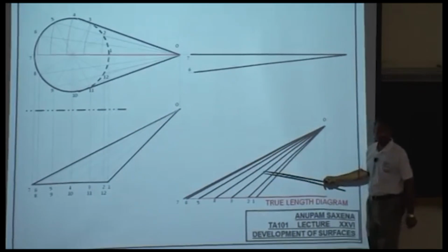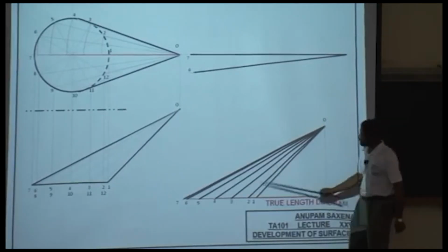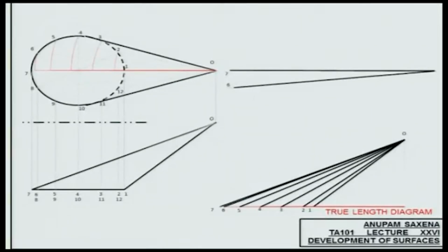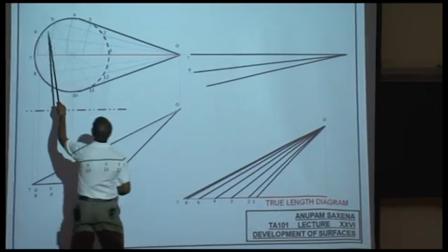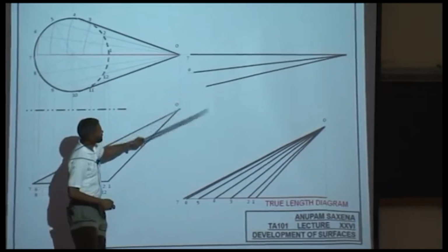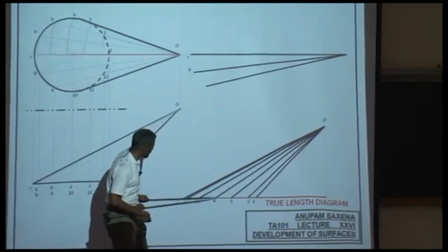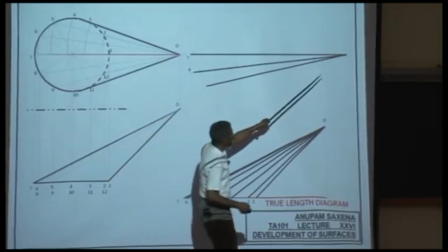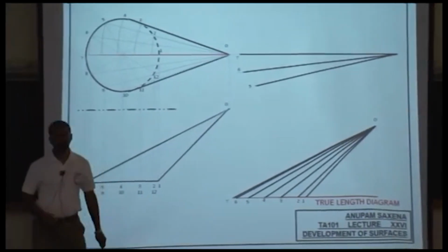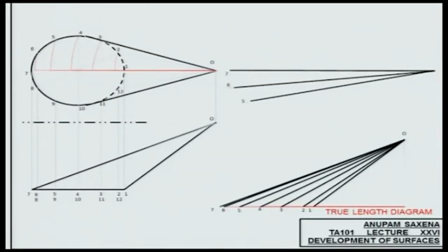you need to choose what? The distance from here up till here. Yeah? 6 is fixed. Number 5: with this distance, cut an arc, and with 0,5, cut another arc with this point as center. 5 is located, and continue.